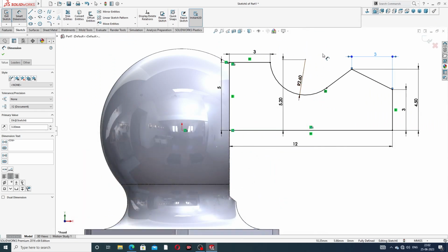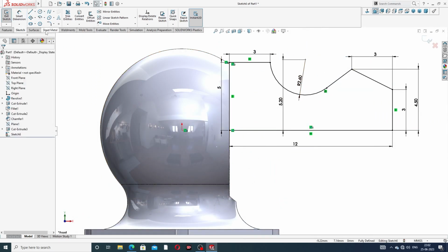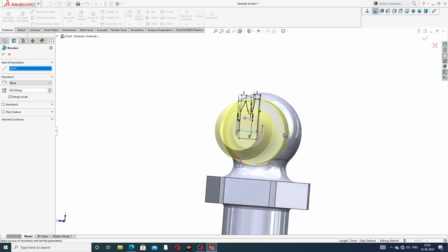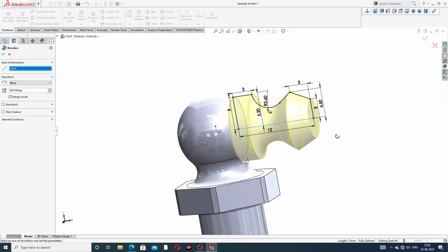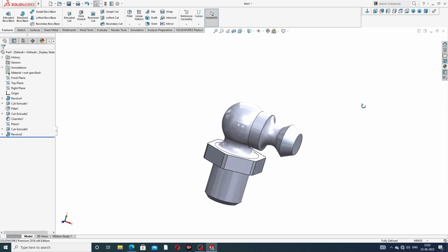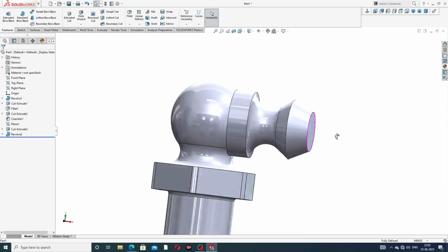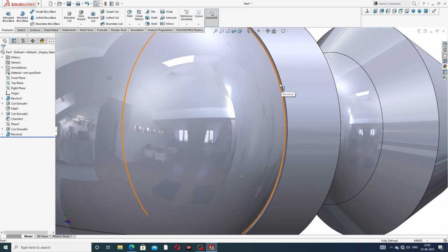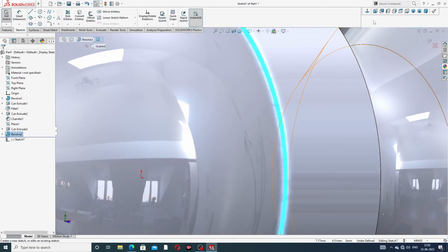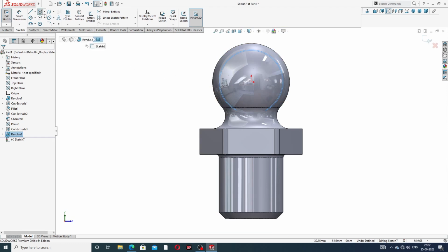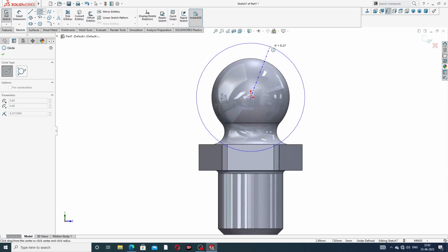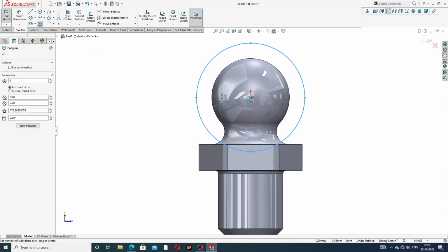Okay, and click revolve boss base and click this. Okay, all is perfect. Looking here, click OK. But some point is very important. This face, this face is a sketch here. Sketch normal, drawing a hexagon. Okay, drawing a circle, a big circle, and also drawing a hexagon.